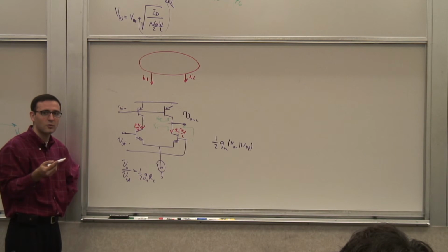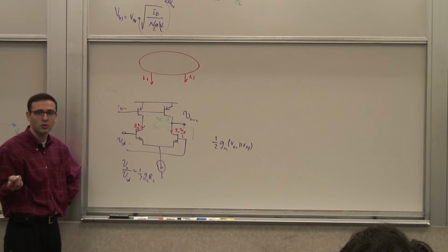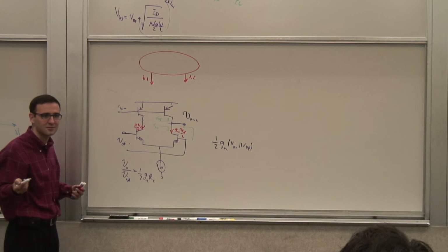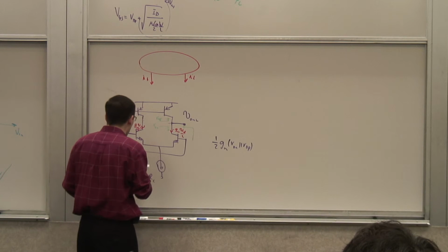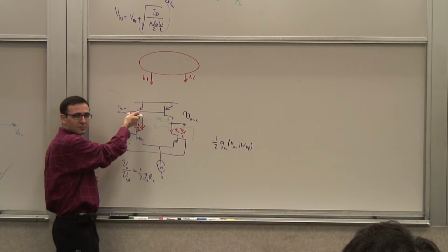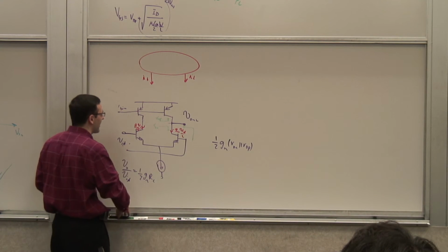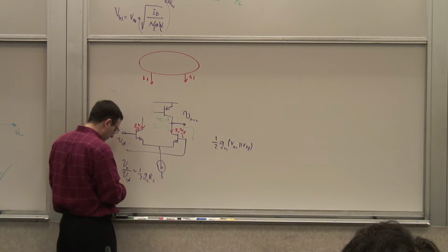No, but do I need the voltages to be equal? I actually don't want the voltages to be equal. It's even simpler than that. It's just a current mirror, right? So I can copy this instead of having this load, because this load is completely useless here, right? So I could remove that and turn it into a current mirror.